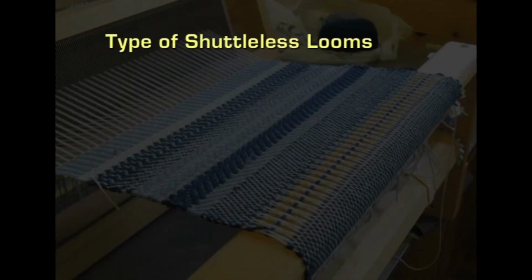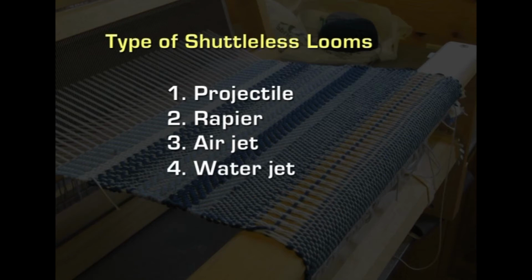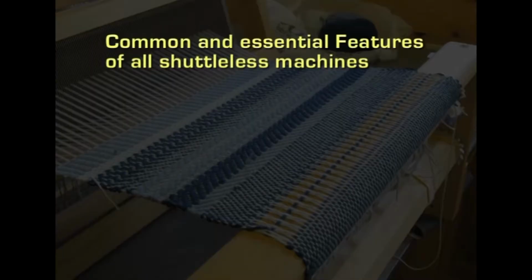Now, let us learn about the shuttleless looms in detail. There are 4 types of shuttleless weaving technologies that are available today. The first one is projectile, the second is rapier, the third is the air jet, and fourth is the water jet. Recently, multi-phase weaving systems have been introduced, but they are still in the research stage. Now, let us see what are the common and essential features of all these shuttleless machines.